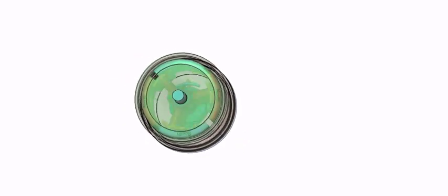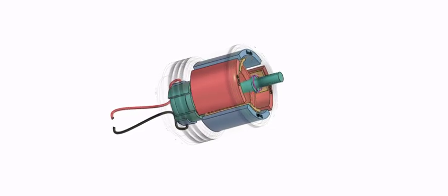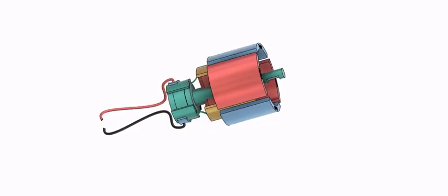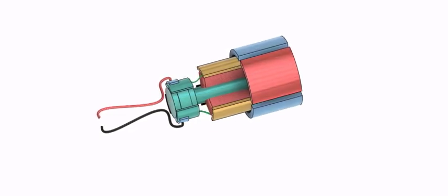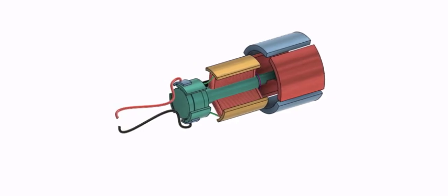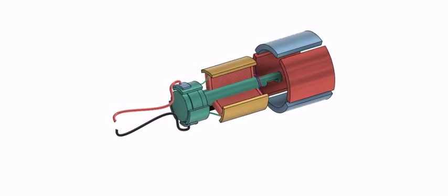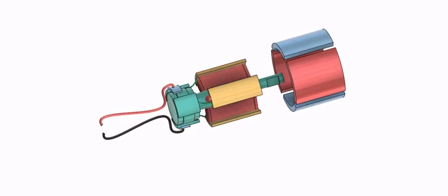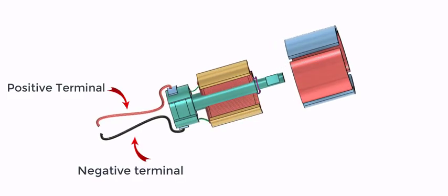The brushed DC motor is again in front of us, featuring four curved permanent magnets and three coils that can only turn into electromagnets when current is supplied. The permanent magnets remain stationary, with two north poles and two south poles located opposite to each other. There are two wires, one attached to the positive terminal of the battery which is not shown and another connected to the negative terminal. The other ends of the wires are connected to the two brushes.